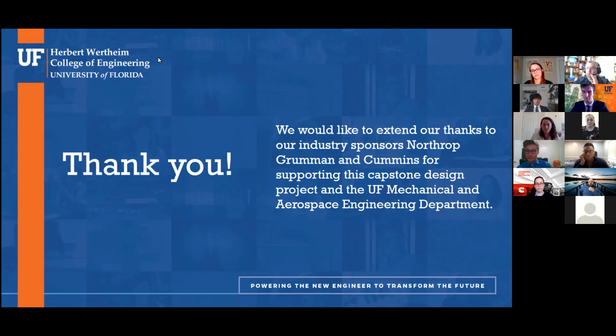So we wouldn't have the same torque. We'd have to spec a lot larger of a stepper motor to accommodate the torque that we would need. So we do have quadruple the torque from having four, as opposed to buying one that's 4 times as big, per se. There's also some slop built in. What I mean is that there's a master one: the bottom left one is actually a line fit with the bearings. Everyone else is a clearance fit, so that there's some accommodation for slop, because ultimately we're not going to be able to get the stepper motors to run at exactly the same RPM. So they're not all bind fit, because obviously the system would bind if they were all the same.